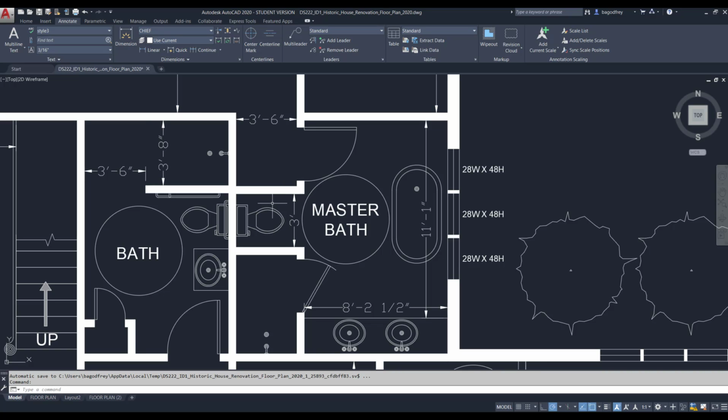So for example, if I dimension this particular wall here that's telling me that's 3'6", these walls are all in line, right? All the way down to the shower. So it's 3'6" here, 3'6" here, as well as in the shower. So I don't have to add that information. And if I put a 3-foot measurement here for this toilet alcove, then I know that this toilet is 18 inches on center. So you could do one or the other. You don't have to have redundant information.